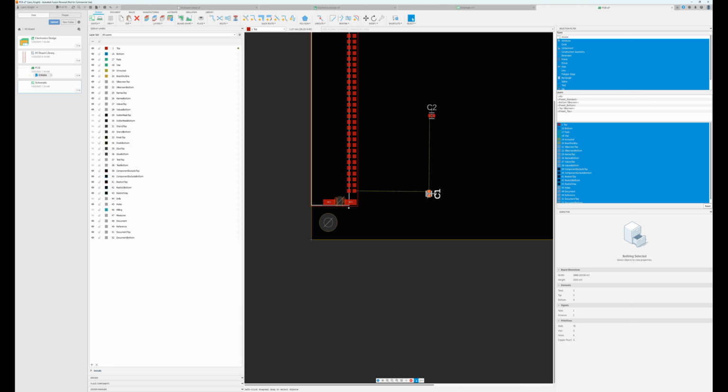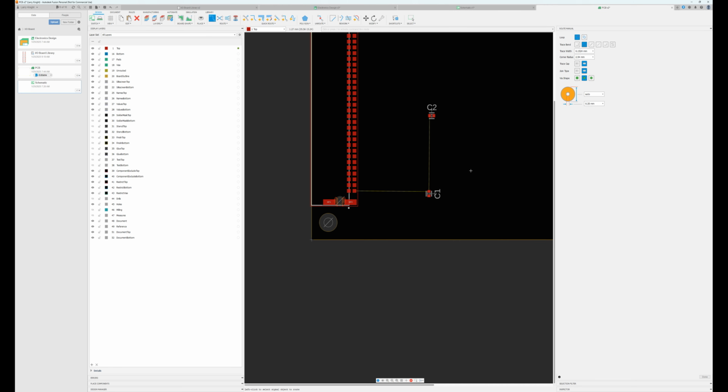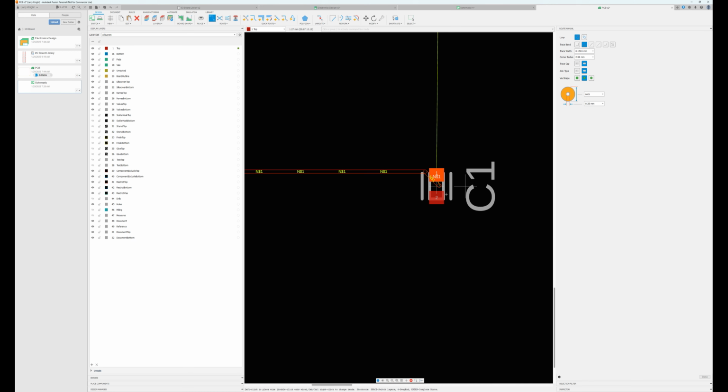This lets you know, and it won't let you place a trace on the wrong side. So then you want to come up here and do a manual route, and you click your pad and come over here, and it won't let you go down here. You can't accidentally or even intentionally place it here, because the schematic says it has to go to this net right here.